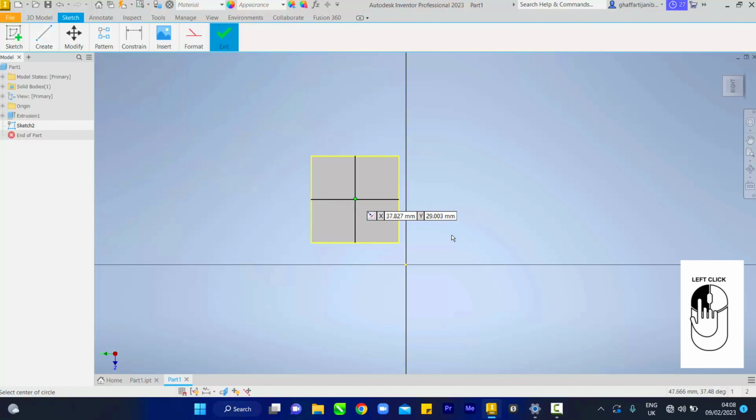You can see I have a green, so you right click and drag. Release your keyboard, you can keep dragging. After you right click and start drawing, keep dragging continuously. But I'll be typing because I'm not perfect at doing that. So let's assume the diameter of our circle is 25 mm. So you press 25 and enter. Can you see it draws the 25 forwards.